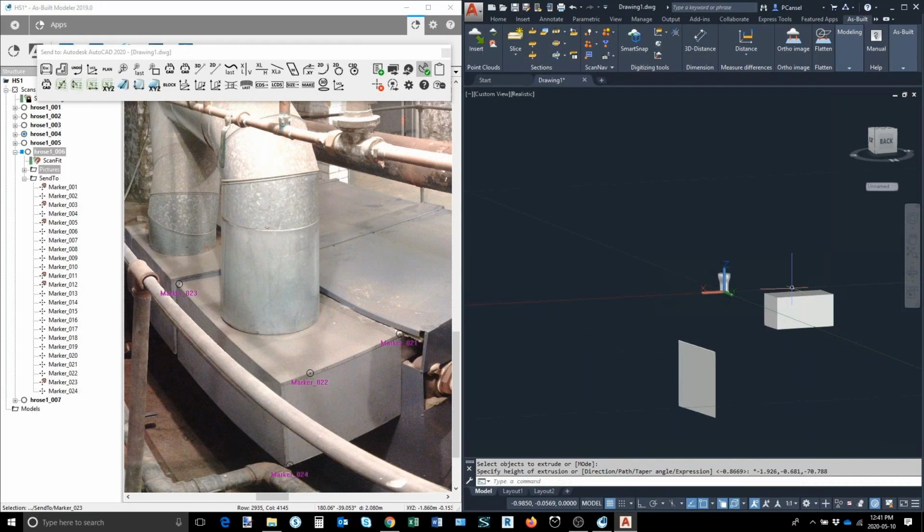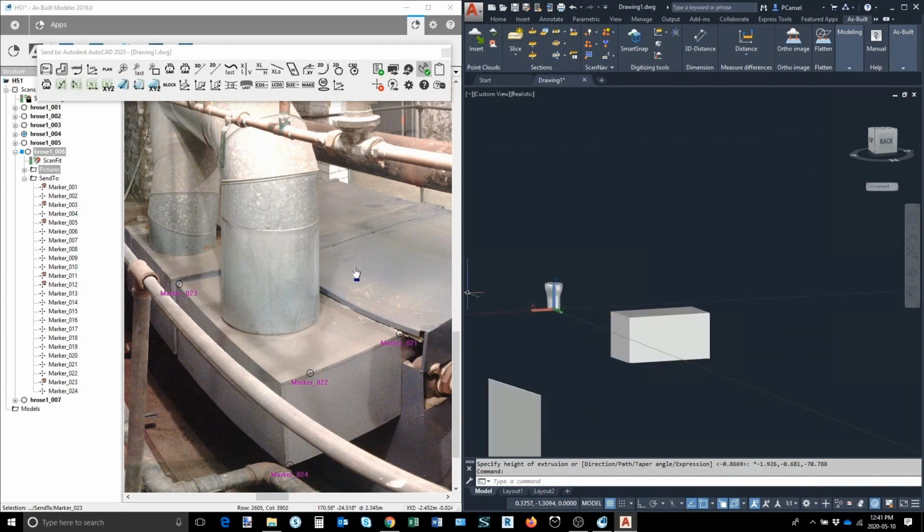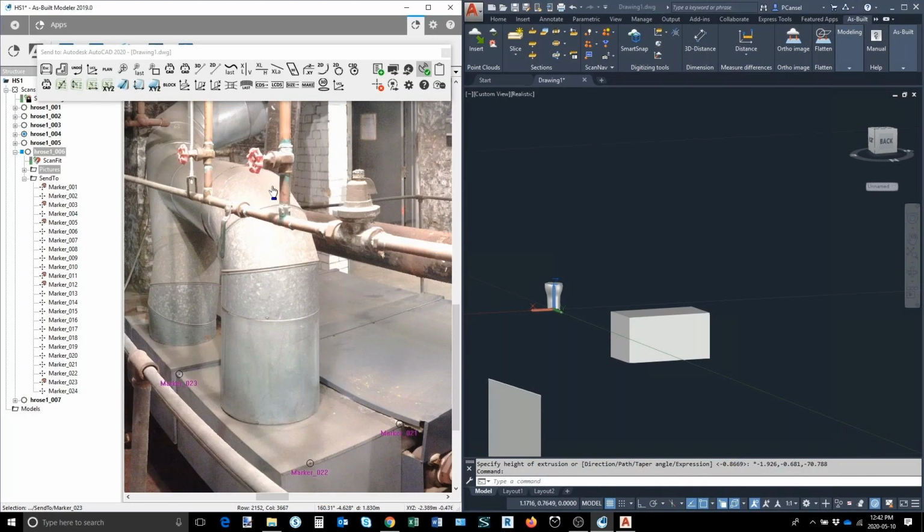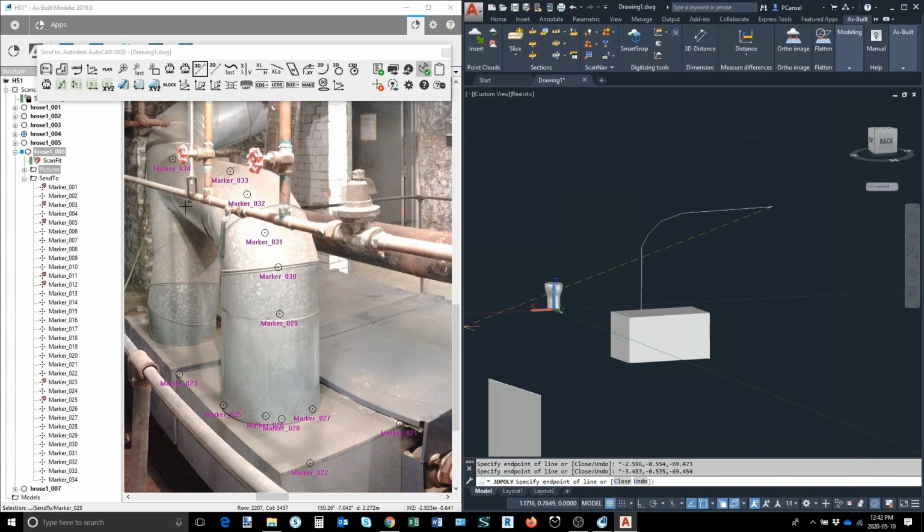And now I turn to that bigger duct that is bending. You will see how easy it can be done. Again, I need a circle here, which I define by making 3 clicks at the base of that duct. Then I need to tell the software the direction and the overall geometry of the pipe. It can be straight or it can be bending. It doesn't really matter. My clicks will show how the duct is moving in 3D space. Just to make it look nicer, I can curve the last segment.